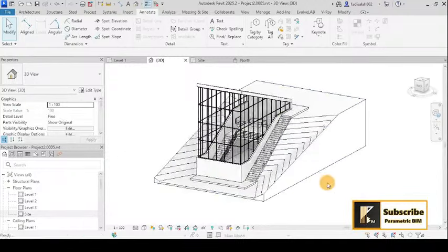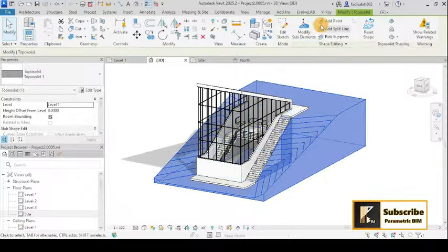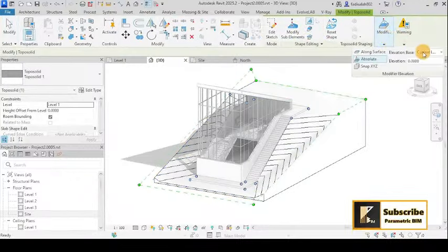I click here and add point, you can see that we have more than one option to select from. I am always selecting the current level, but you have the opportunity to select the project base point, the survey point, the internal point, or the top plan. You can experience that by playing around with this and see what the difference is between these.